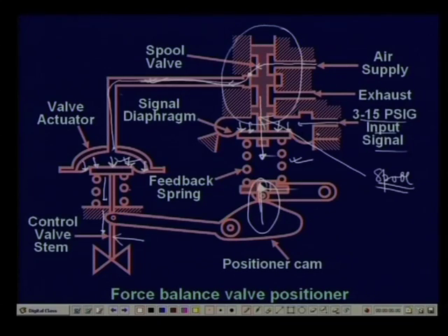Since this is an applied pressure and the spring force depends on the displacement, as long as this force is not balanced, say when this force is higher, the valve will start opening and this pressure will keep increasing. As it keeps increasing, this is trying to come down, and therefore this is going to go up, increasing the spring pressure. The spring pressure will actually balance this force when a particular displacement of this spring takes place, and by the mechanism, a particular displacement of this spring implies a particular displacement of this stem.